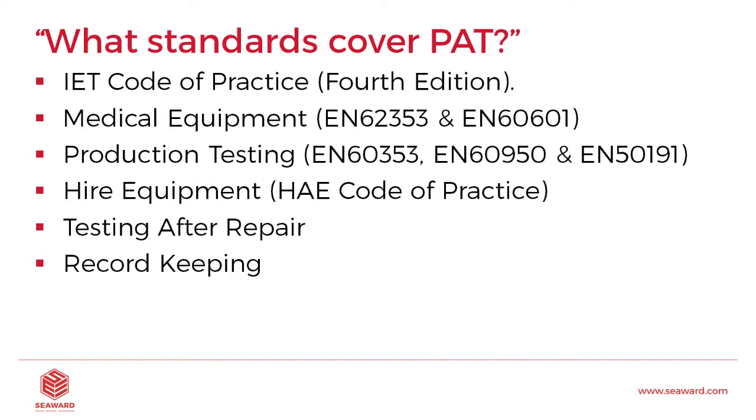And then of course the most important thing of all is actually the record keeping itself. Absolutely vital that you keep all your records of failed equipment and equipment that's passed. If you are carrying out repairs, it is very highly recommended that you don't carry out the repair and then test it and pass it. Log the failure, then do the repair and carry out the test, just so you have a record and can keep an eye on failure rates, on equipment types and things like that.